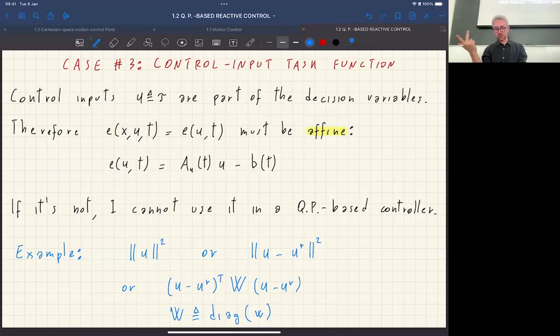That's in practice useful, because typically your robot doesn't have all joints with the same motors. So at some joints you have motors that are much more powerful than at other joints. So it makes sense to assign a higher weight to joints that have a bigger motor, basically, so that they can apply more torque.